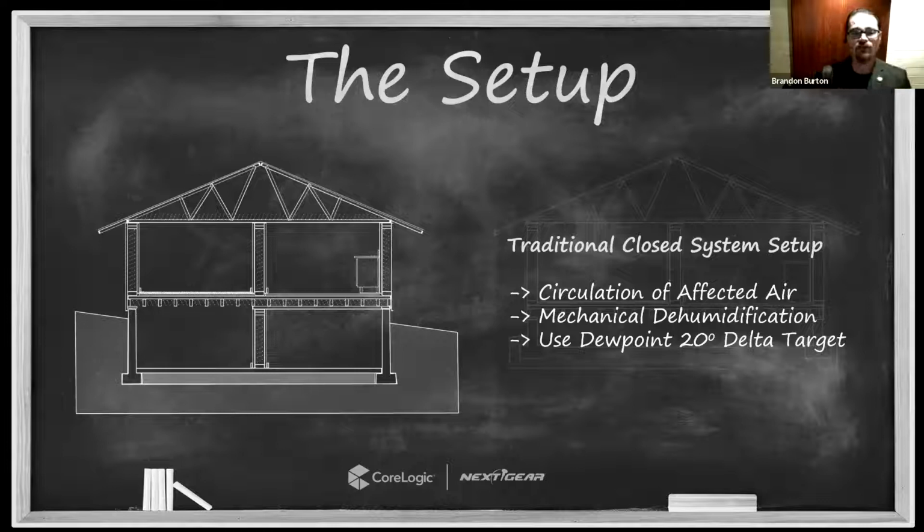And what that may drive you to is the type of mechanical dehumidification that you're using. It may very well alter that scheme. At a very minimum, in a basement area with lots of cement, we should be dealing with low grain refrigerants, right? And we've talked a bit about dehumidifier technology in a previous episode. The other technology that we may dive into in this case would be desiccants. If it's necessary to get me down to 38 grains and your low grain refrigerants just aren't doing it, then we may want to drive down to a desiccant dehumidifier.